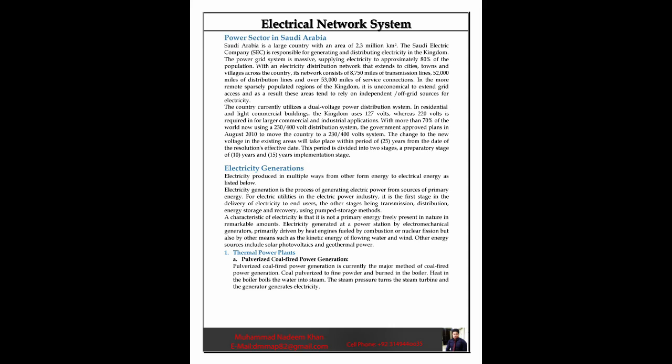industrial applications. With more than 70% of the world now using a 23400-volt distribution system, the government approved plans in August 2010 to move the country to a 23400-volt system. The change to the new voltage in the existing areas will take place within a period of 25 years from the date of the resolution's effective date. This period is divided into two stages: a preparatory stage of 10 years and a 15-year implementation stage.